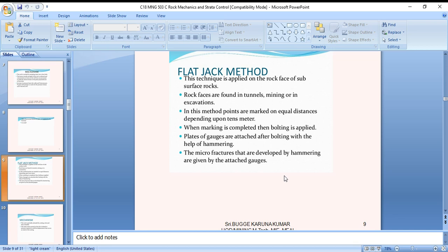Systematic errors are consistently either positive or negative, and they can be evaluated only by calibrating against a standard. Systematic errors are caused by factors such as physical damage, loss of calibration, temperature, humidity, and other factors external to the errors that are inherent to an instrument.